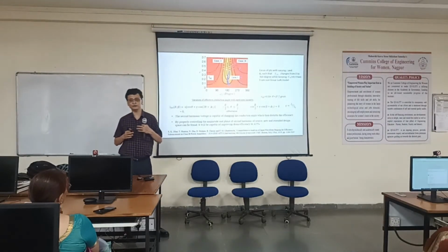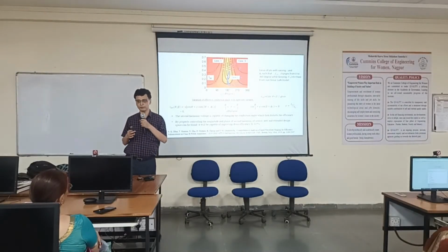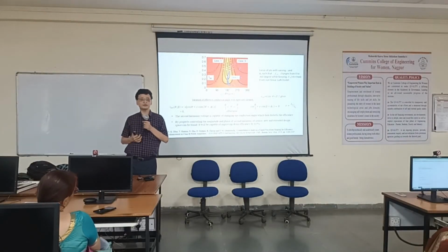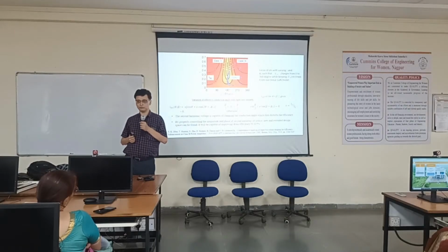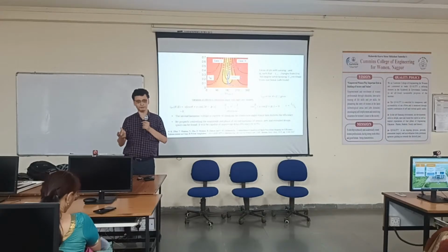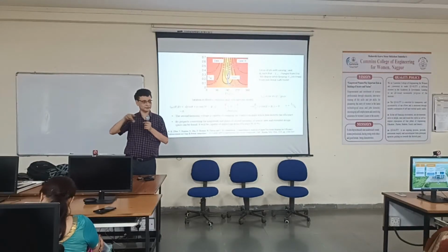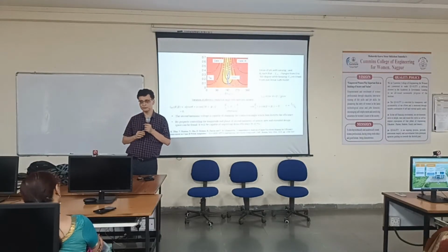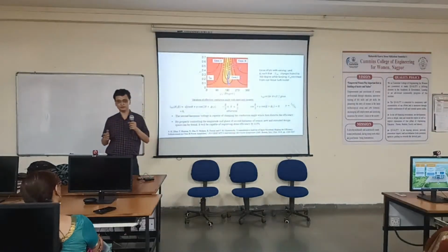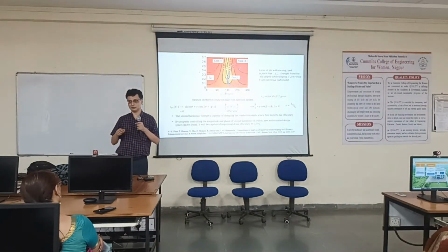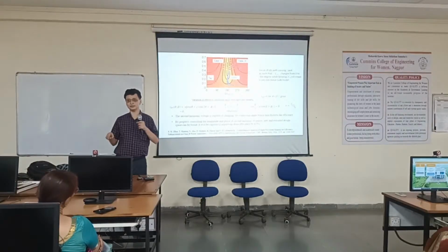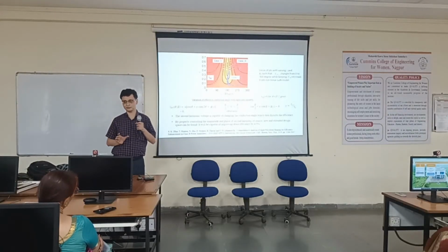Suppose I ask you to make a circuit using op amps. Suppose I ask you to make a non-inverting amplifier using an op amp. How do you do that? You first take the op amp, you put the load, and then find the values of the feedback resistances, and then you find out the gain, right? Here we are doing the mathematics first, and then we are adjusting the circuit to fit that mathematics.